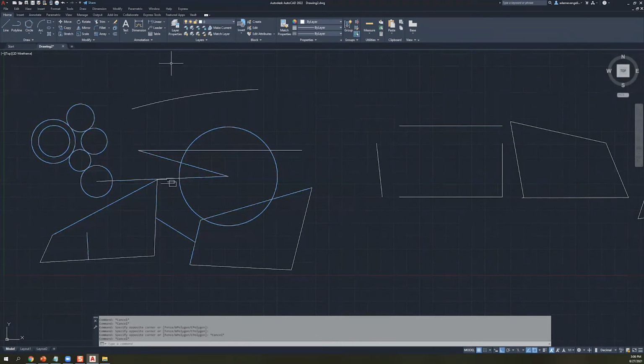And so really simple stuff, all of this is super classic, and all of these commands end up appearing in Inventor as well, right? Like move, rotate, copy, mirror, a lot of these translate directly into Inventor in various ways, which is an interesting thing to note as well. But that said, what the heck does move do? It might not work the way you expect it to, but I click move, and what is it even telling me to do? There's no dialog box. Well, if you look at the bottom, it's telling you to select objects. So yeah, I want to select all these objects. And I'm going to use my crossing window, for example.